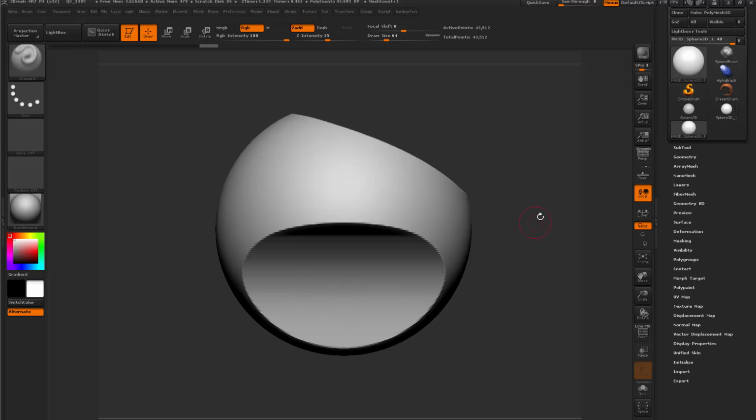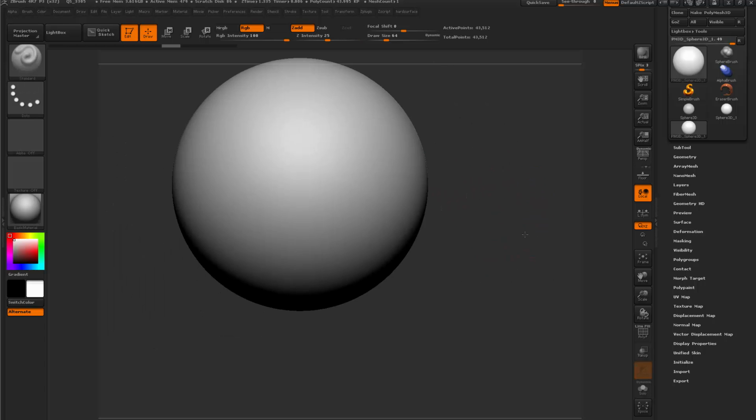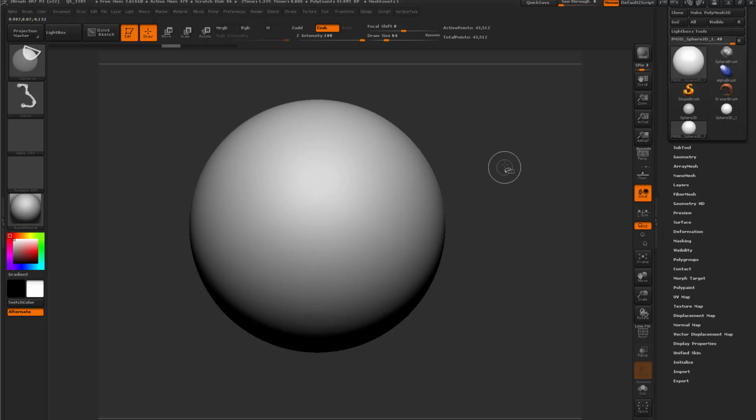The way to use Clip Curve would be holding down Control Shift, and then you can drag out a line. After the line is created, you can release the Control Shift keys. You can press Alt once to change direction, press twice to have a sharp turn, holding down space to move it.